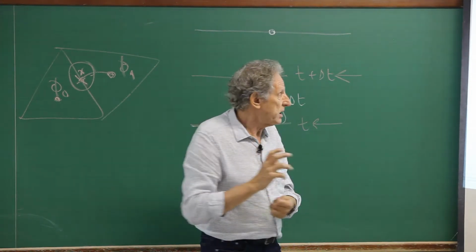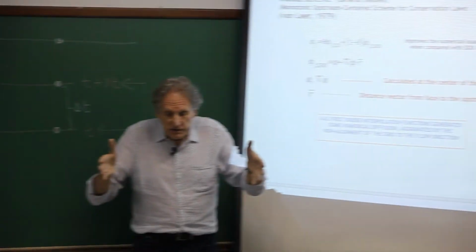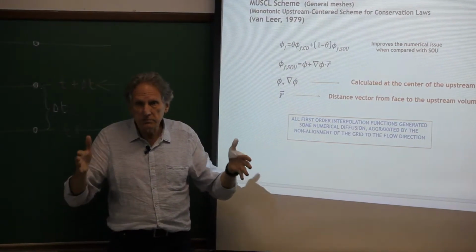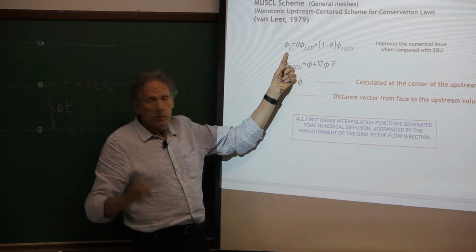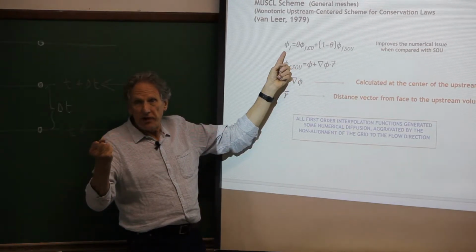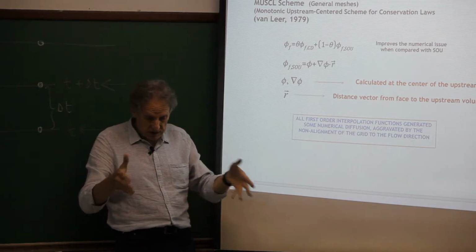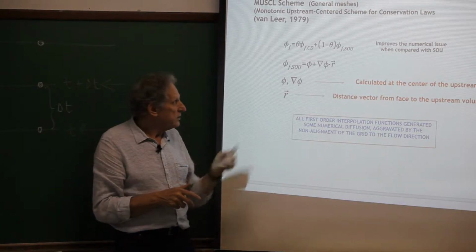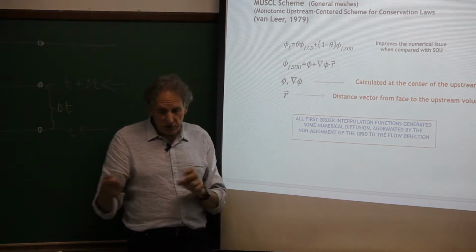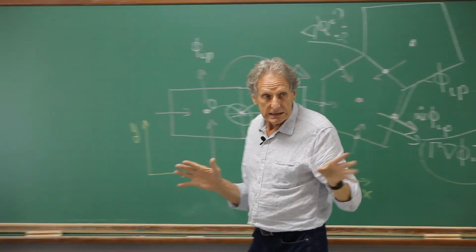So theta equal to 1 is saying this is a pure diffusive problem, because if theta is equal to 1, the calculation of phi at the integration point is using central differencing, which is very good for diffusion problems. So this theta is related to the weight that you want to give to the diffusion or the advection. You know? It's clear?